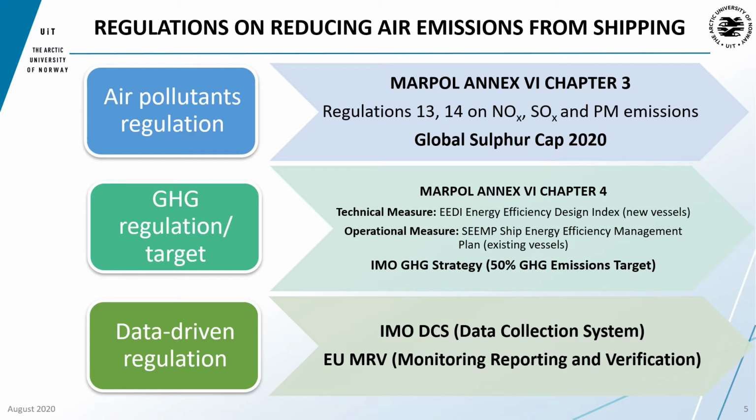In terms of greenhouse gases regulation or target, greenhouse gases emission are addressed in MARPOL Annex 6, Chapter 4 with two measures. EEDI, Energy Efficiency Design Index for new vessels, SEEMP, Ship Energy Efficiency Management Plan for existing vessels.